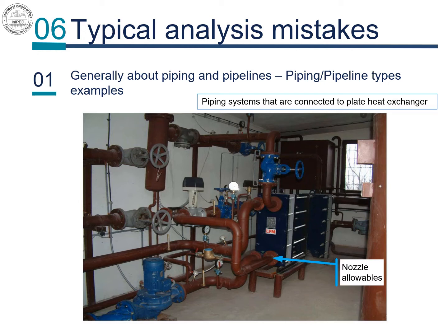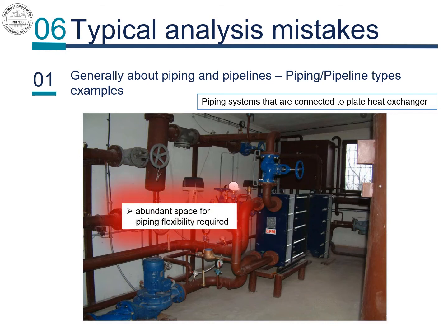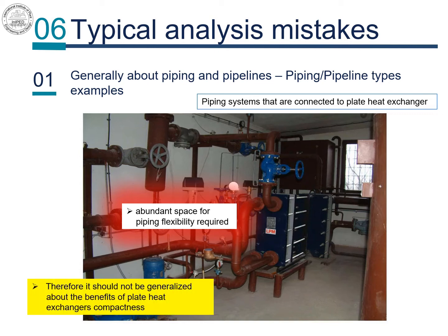in piping design. However, if we decide to count on the benefits of compactness, we should not forget on the other side also the need for provision of excessive piping flexibility. Hence, unless a feasibility study is conducted prior to deciding to go via the plate heat exchangers route, the rushed, overall conclusion about benefits that was assumed above might be overrated, and should not be generalized.